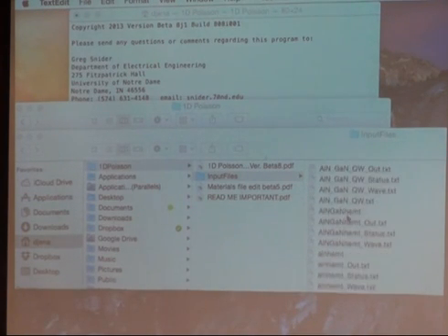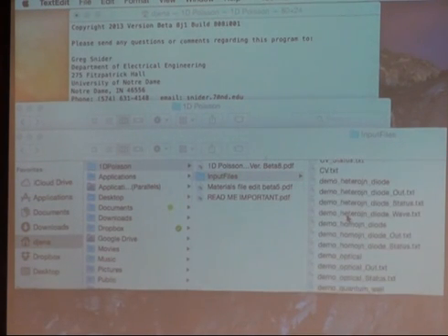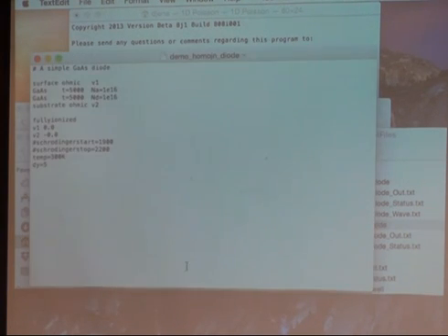Now let's do a couple of demos. I had planned to show you something very simple first, say a homojunction diode. So what is the input file? Very, very simple. It's just these lines. This is how you define your layer structure. So here's a gallium arsenide diode. The substrate is an ohmic contact. I have an ohmic contact on the bottom, so it cannot be semi-insulating.